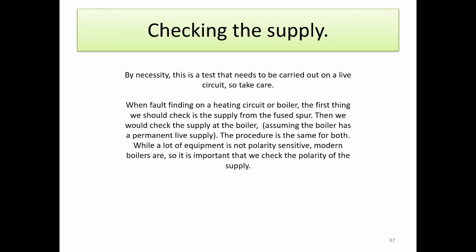The procedure is the same for both ends. While a lot of equipment is not polarity sensitive, in other words, it doesn't matter which way around the live and neutral are, like a light bulb, they'll still work. Modern boilers are polarity sensitive, so it's important that we check the polarity of the supply.